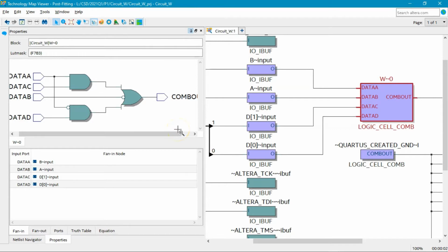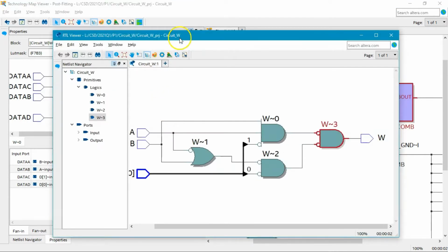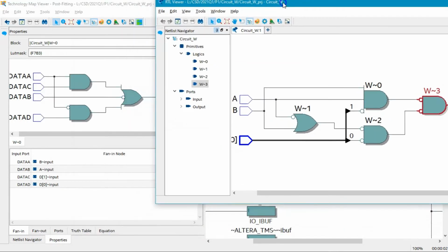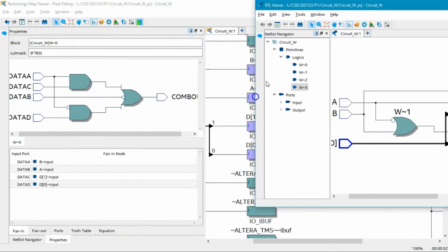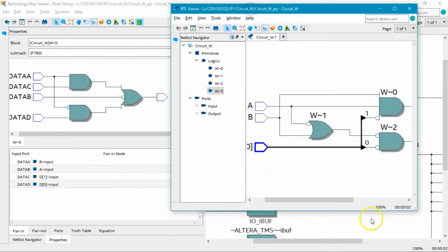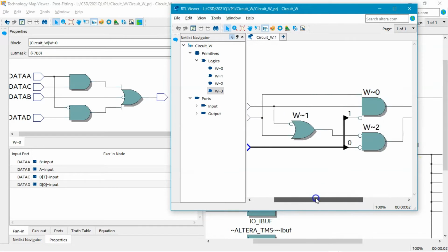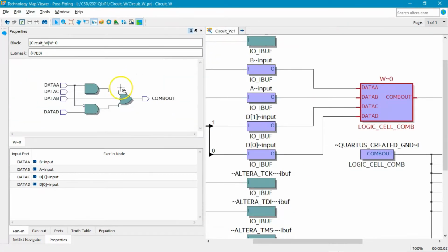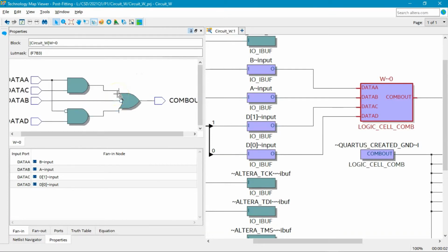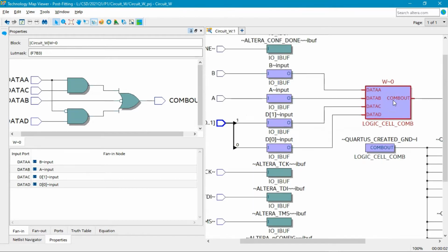So here you are, one circuit, the one which is synthesized for real, and the other circuit which is ideal. Look at this. The ideal has to be what you had in mind in your VHDL, right? But the technology view will depend on the devices that the FPGA has internally to generate circuits, basically lookup tables and RAM memories and the like to implement this logic.